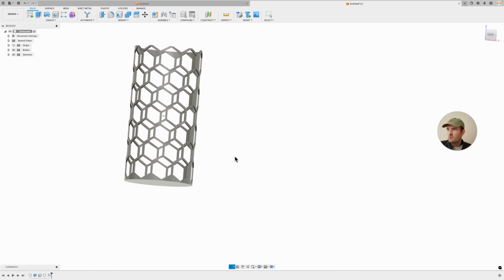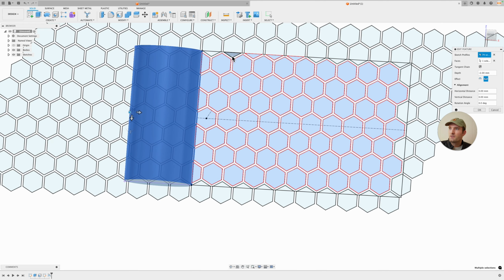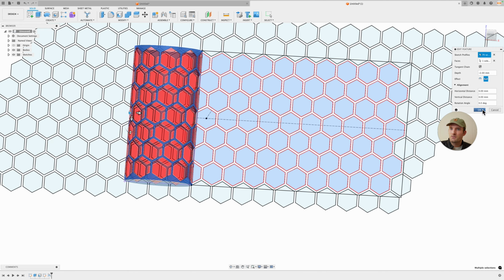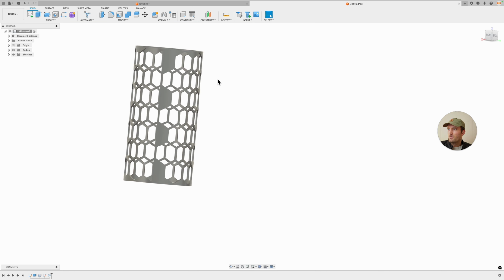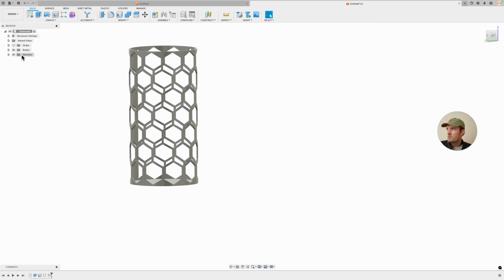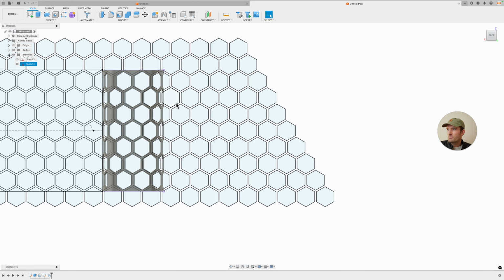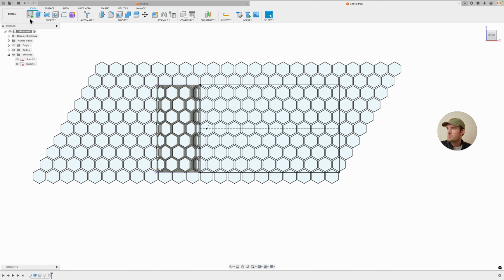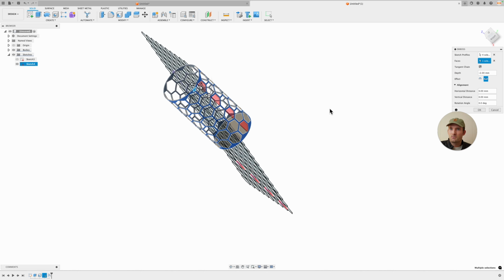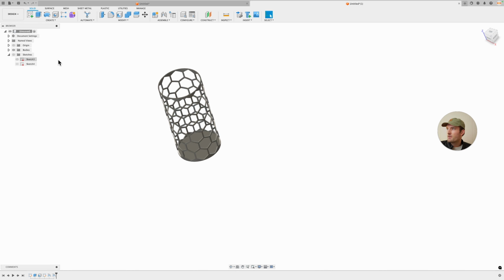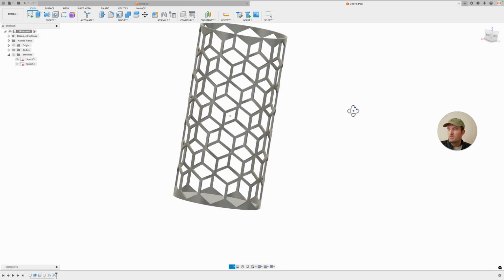And the last thing we want to do, actually we skip some there, so let's edit that. And obviously you can do this however you think looks the best. So we missed these, and that was because of that error. So essentially you just need to redo the same thing again, just for those ones that we didn't do, which were the ones on the far right here. So we're going to do the same thing, create, and then emboss here, and then select those surfaces, make sure you cut them, and then click OK. And then hide the sketch, and now we have our part.